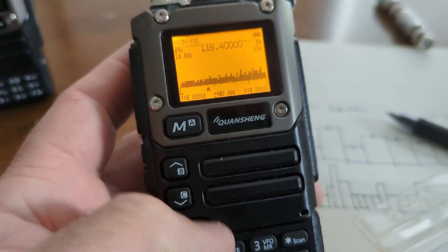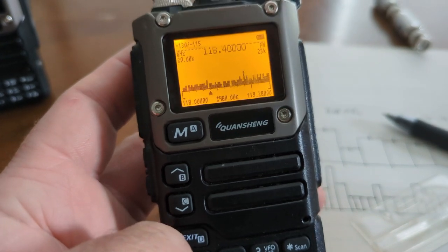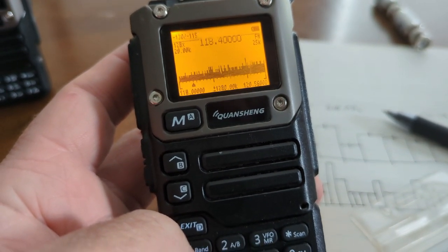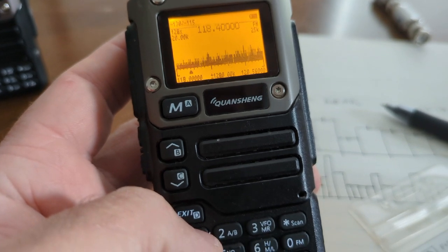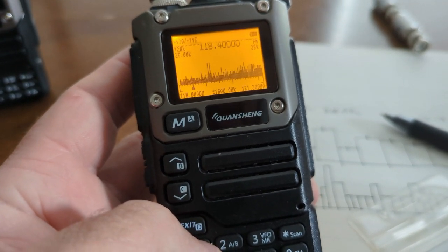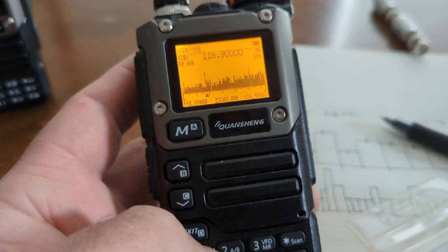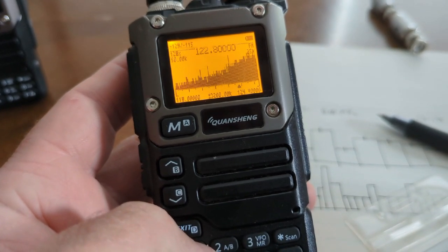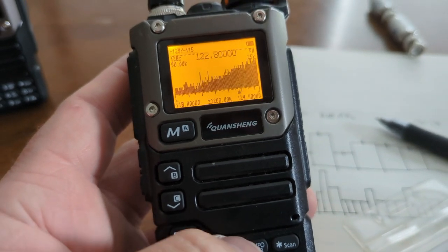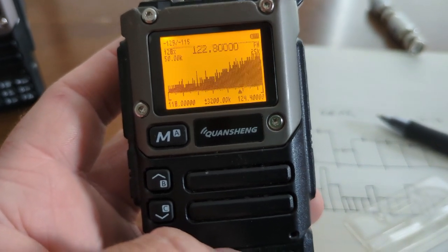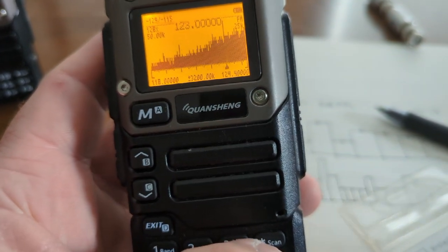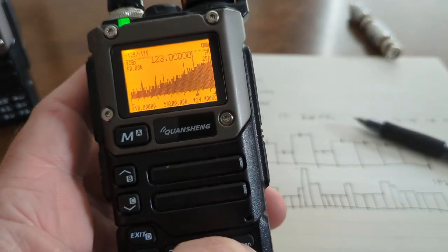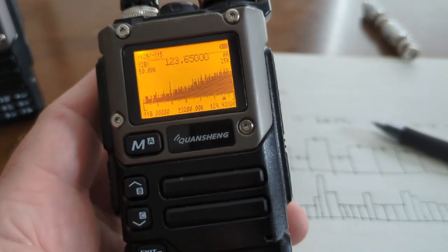So I'm going to increase my number of bins, do a much slower scan. 120. And now I'm going to have to increase my bin size. And I might not be able to get the entire frequency in here. So the other thing I'm going to want to do is, aircraft use AM instead of FM modulation. So I'm going to change that using the 0 key here. Switch it to AM.